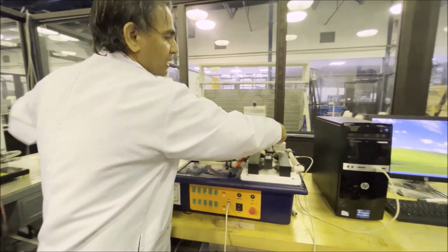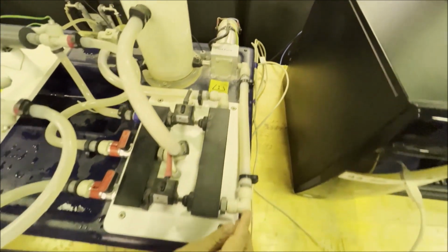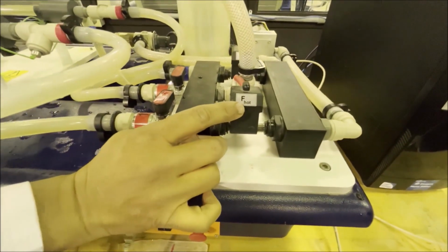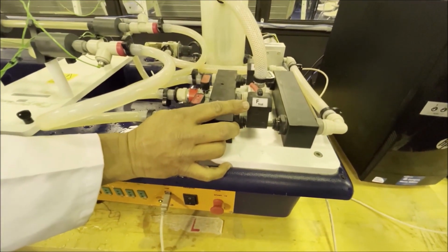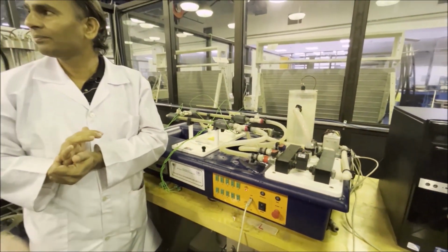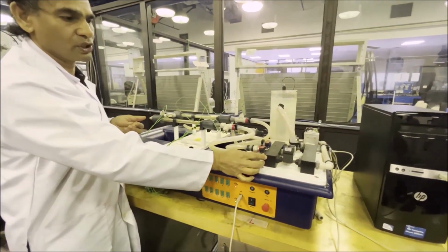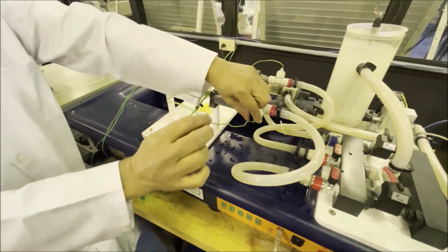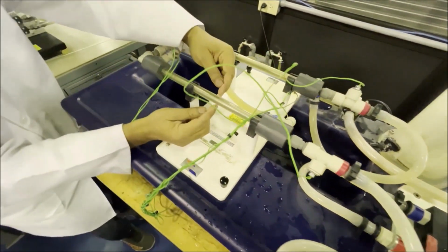Then this hot water is pumped here by using this pump, and it will flow here. So this sensor will give you the volume flow rate, F hot. Hot water is flowing here, and this sensor will give you the volume flow rate, discharge, in liters per minute. Discharge, you study in fluid mechanics. So hot water will come here, and we can measure its temperature by this thermocouple. Hot water will flow through this inner tube.